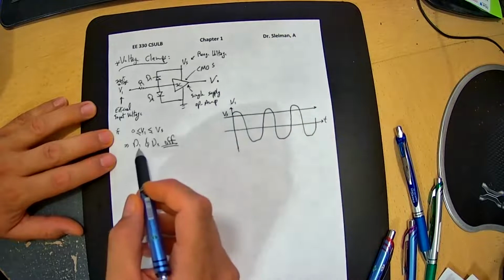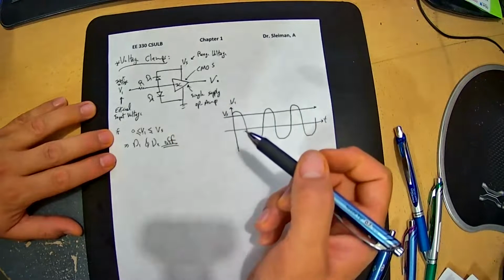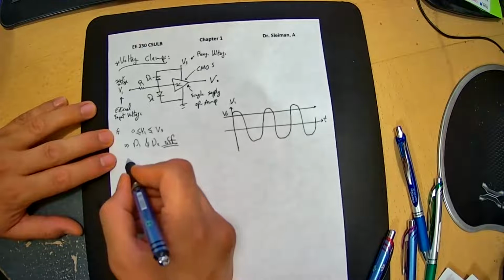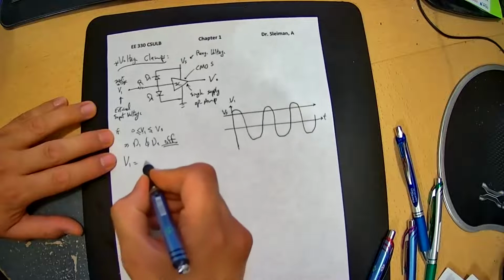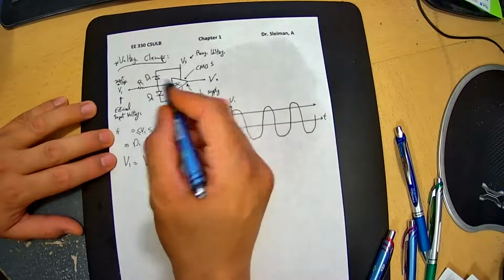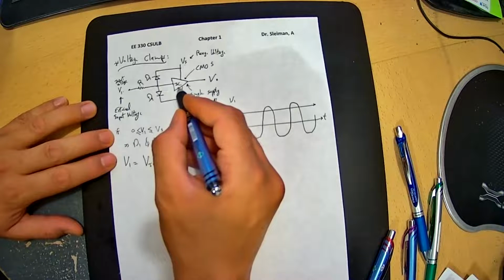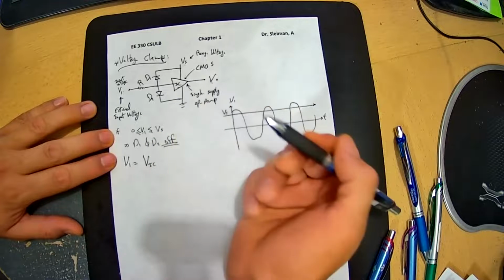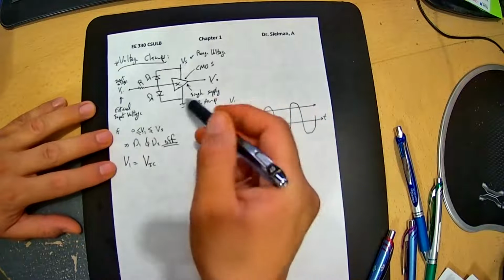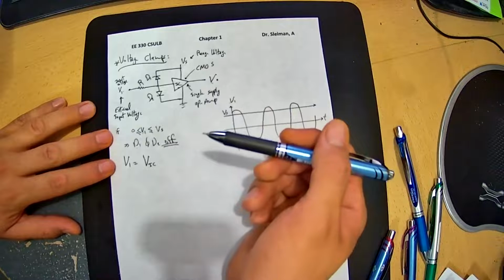So most likely, both diodes will act as a clamp. So in this case, we're going to elaborate that V1 is equal to V for the IC. So most likely, the input voltage has to match the range of the IC voltage, so the output voltage will be safe within the range that the data sheet specifies for this IC to operate.